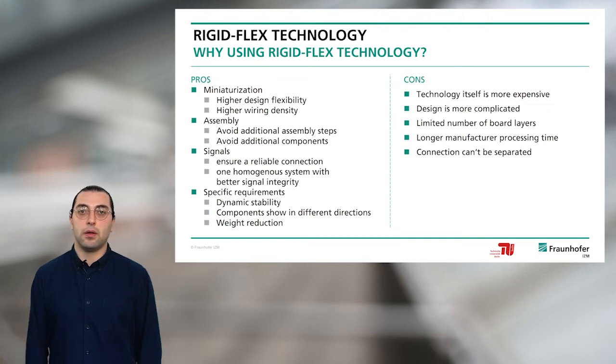To design the hardware, we have more considerations, and it's more complicated. The number of layers is limited in comparison to standard FR4 rigid PCB design. The processing time is longer because we have additional processing steps, and of course, once designed and connected, the connection can't be separated.